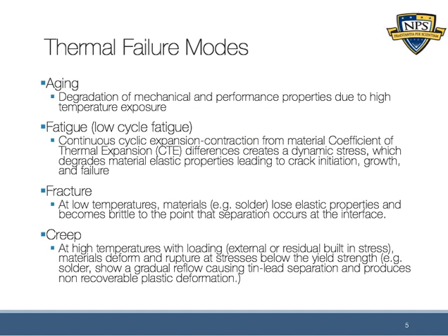Essentially when things expand and contract, they change at different rates, and that induces stress in the material, and over many cycles it causes some sort of crack, which of course then grows over subsequent cycles, and then eventually breaks apart. Some sort of actual yielding occurs at some point.